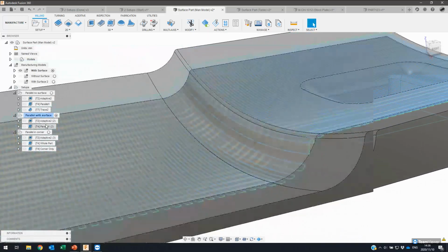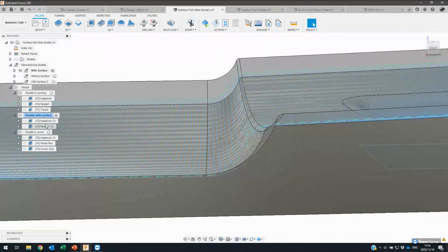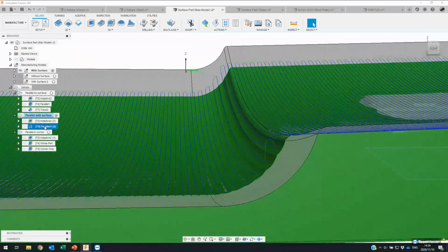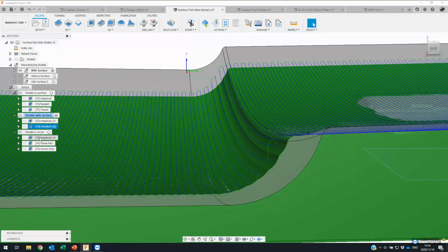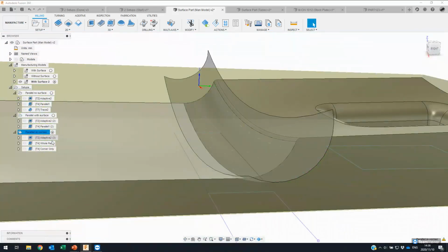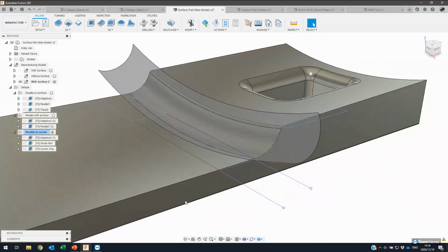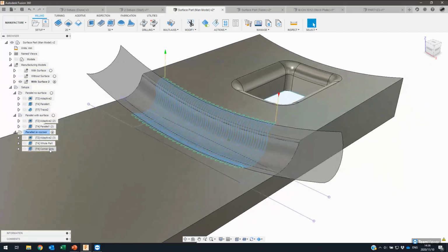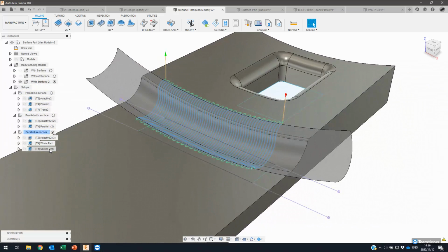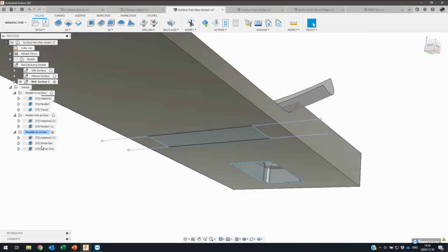However, if we look at where the parallel toolpath climbs the wall, we have quite a big step here, and it leaves us with some large cusps on the part. So we could use, let's go to the third setup here. We could use that surface, and in fact I have a combination here of using that surface just in the corner to machine on that surface, as well as using the sketch to limit where I am actually machining.